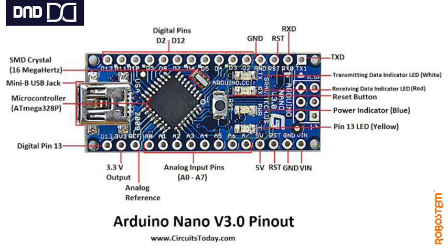These are the 4 LEDs we are having: TX, RX, PWR, that is power, and the last one is 13. That means the digital pin number 13 LED, which is interconnected to digital pin number 13, will glow accordingly. When the data is coming in, then it is RX. When the data is going out of this board, then it is TX. If the power is supplied to this board, then PWR, and if you are powering digital pin number 13, then the pin 13 LED, which is yellow in color, will glow. So this is about the Nano.